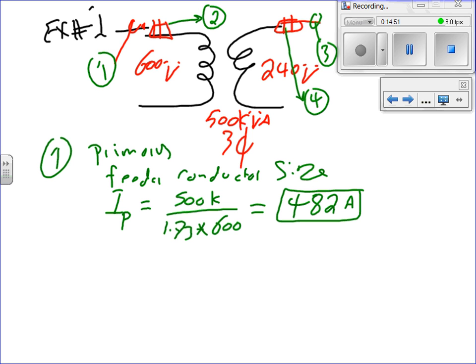From now on, everything that we do is line to line. Line current, line to line voltage. The coil current and all this good stuff, forget it. That's where the basics begin. Okay, great. Then from here, this is the full load current of a transformer. Now here's my question for you guys. I need to size a conductor that can carry this current.